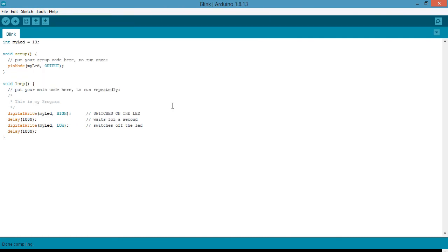And let me just quickly say this: sometimes you may connect your Arduino Uno and you don't find it in the Device Manager. If that is the case, just notify us on the Classroom platform. There's a fix for that, but I will not be explaining it in this video. So now I am going to upload. This is the upload button. I'm just going to click it, and it's going to upload the code to my Arduino. It's saying uploading in the status here, and it's done uploading now.